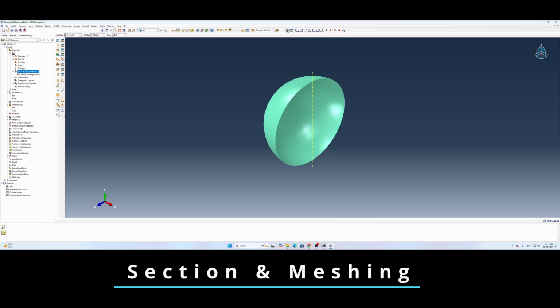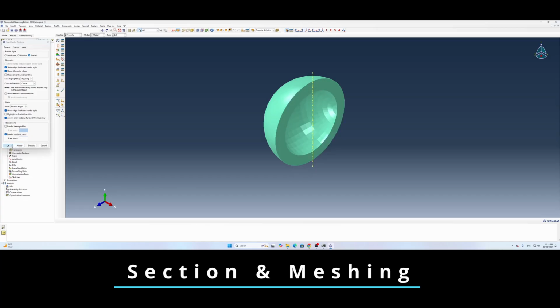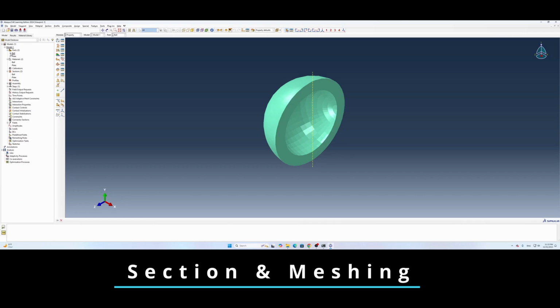Let's see the cross section, and then we can see the thickness rendering. So view, part display option, and then render shell thickness. All right, so everything is inside my geometry. So this looks good. So the next thing is that we need to apply the section to our plate.